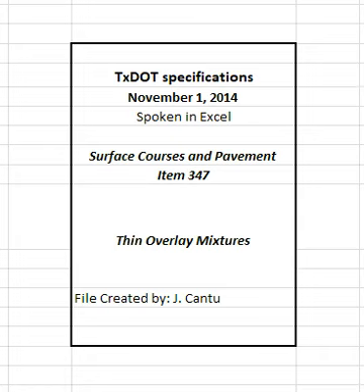4.4.2.2.5 Testing the trial batch. Within one full working day, the engineer will sample and test the trial batch to ensure that the mixture meets the requirements in Table 8. The engineer will mold samples in accordance with Tex-242-F if the contractor requests the option to have the department perform the Hamburg wheel test on the trial batch mixture to verify compliance with Hamburg wheel test requirements in Table 7. The engineer will mold samples for the overlay test in accordance with Tex-248-F to verify compliance with the overlay test requirement in Table 7.